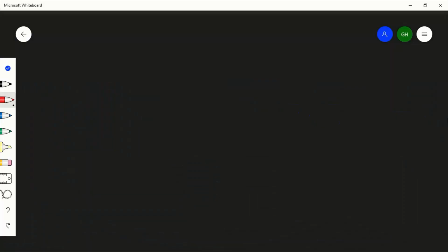Alright, so we know that torque is equal to force times distance times the sine of the angle between the two vectors. Now, since this is going to be 90 degrees, it'll be 1, so we don't care about it anymore. And from this, we can say with confidence that force is equal to torque divided by distance.